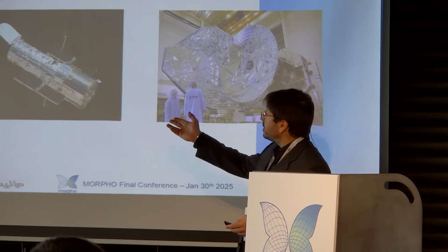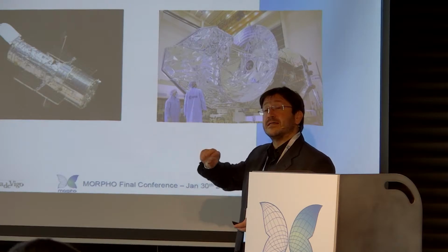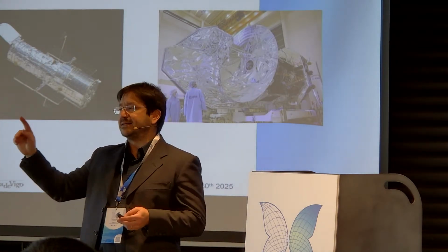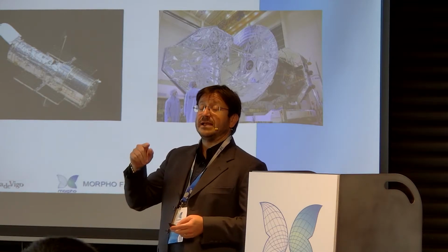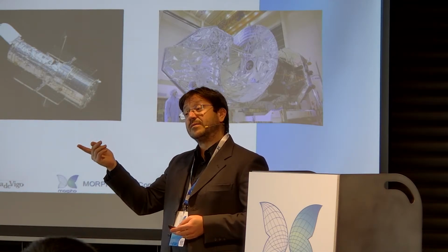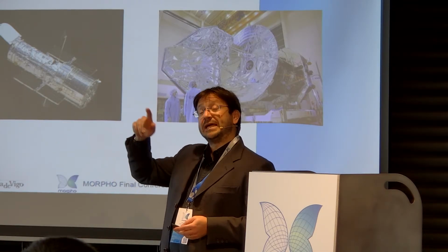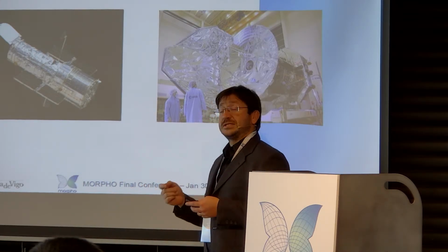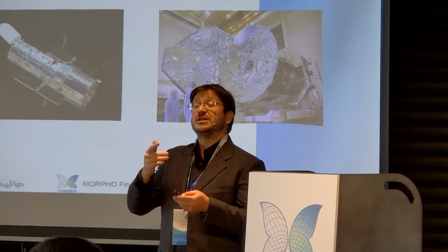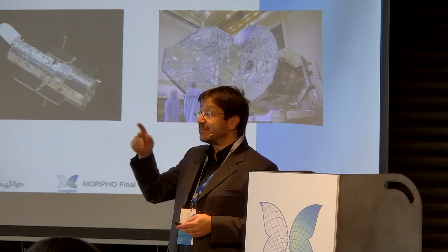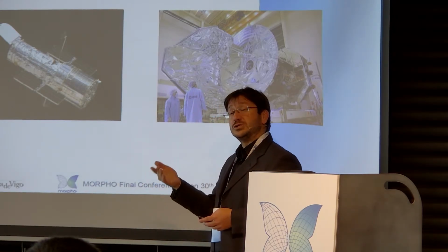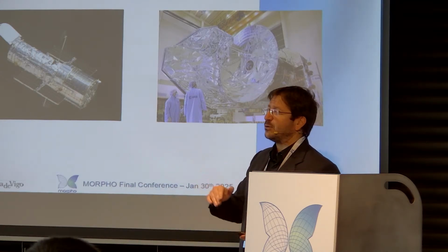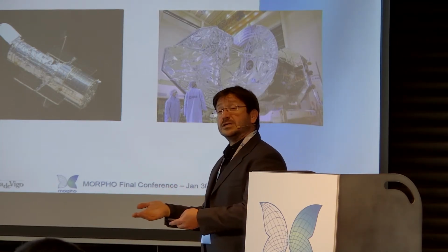The Hubble Space Telescope had an unexpected thermoelastic problem called thermal snap: when it passed from the light to the shadow, or from the shadow to the light during the eclipse occultation, the solar panels, not being so stiff, had a thermal snap, and it messed with the control system, so it lost stability. Hubble could be repaired and reserviced, and it got new solar panels.